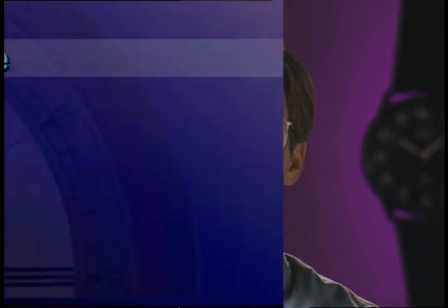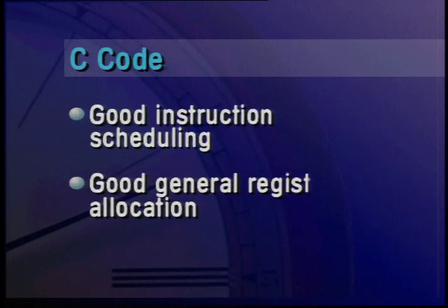Low-level C code is produced by VCS, and the host machine's C compiler is allowed to optimize it. That has some pretty good consequences for the quality of the code generated, because there have been literally hundreds of man-years of effort put into generating good C code for any given hardware manufacturer's C compiler. There is no hope that you would ever put that kind of effort into an HDL compiler's code generator.